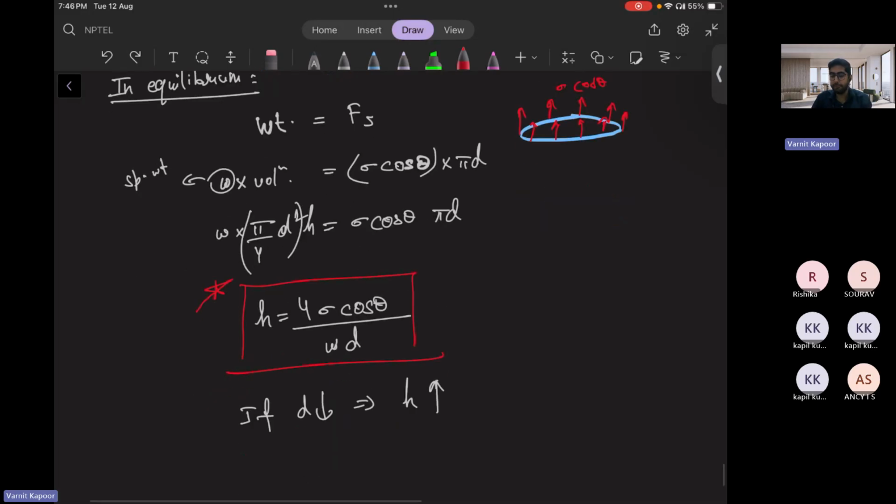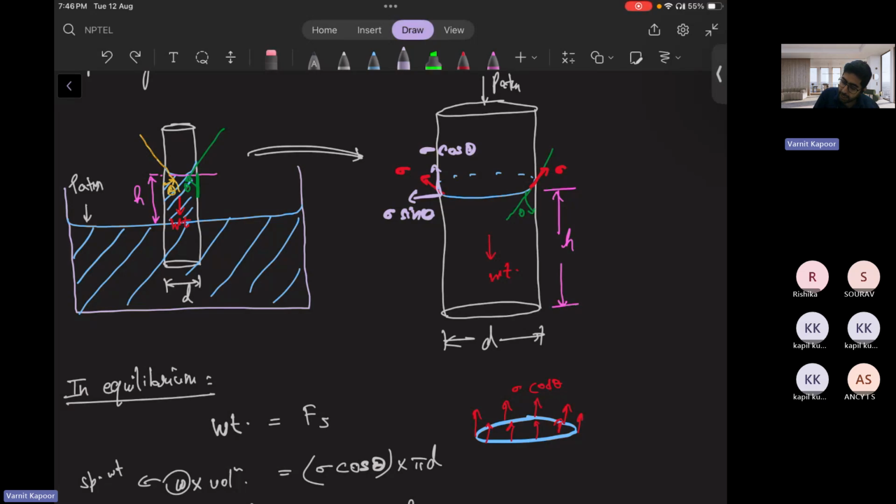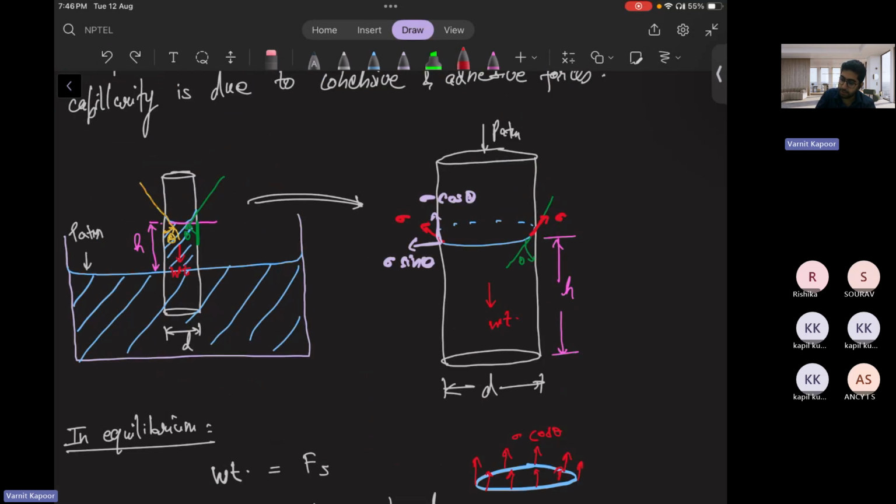Now you have got the height. If I ask any one of you, what will be the pressure at this point A? The question can come: the pressure just near the meniscus, basically. Outside it is P atmosphere, but what will be PA? The pressure at this level is at height h. PA plus, if you go down, the pressure increases. That is hydrostatic pressure, rho gh.